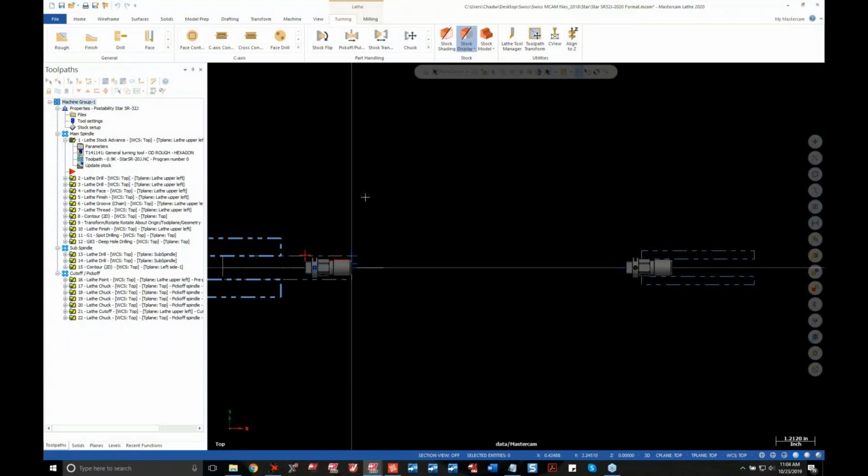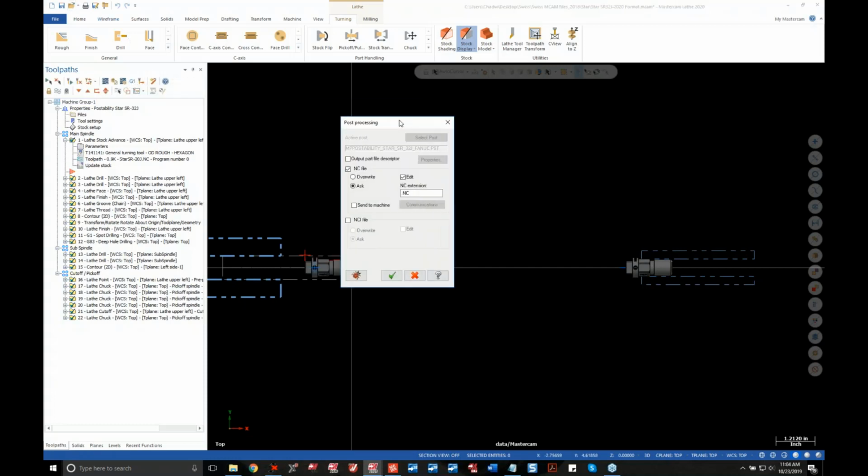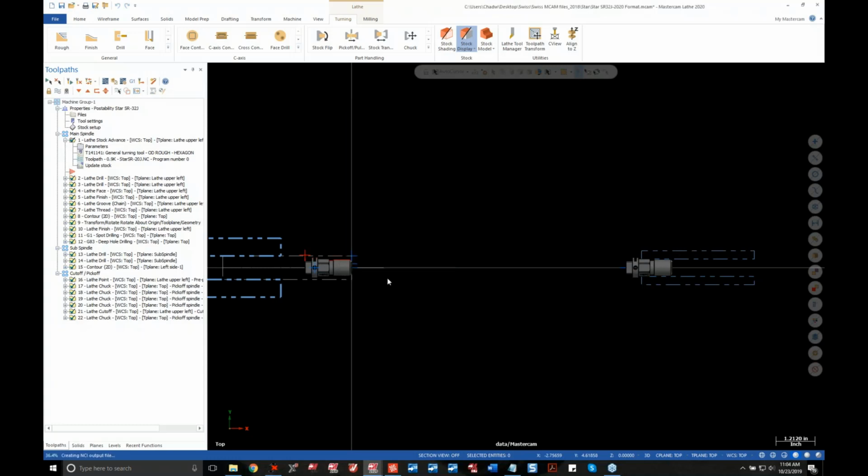You'll notice we did work on the main, we did work on the sub, then we went back into the cutoff pickoff. That's back on the main, so you can bounce back and forth on these. Like I say, the big thing is you just want to get the sequence of your ops for each spindle in the right order. Now for the important part, when we actually generate the code, that's going to be taken care of in here. I'm just going to generate this live. Come in here, tell it to generate the G-code.